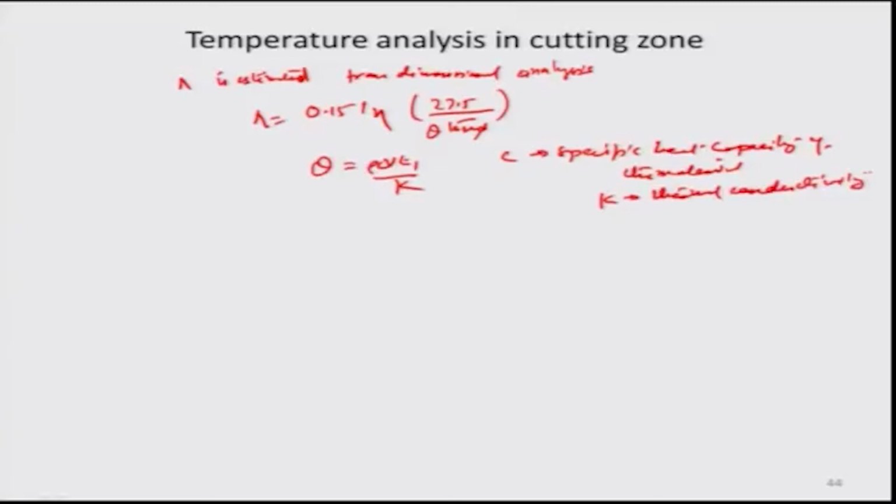So you have to create these non-dimensional quantities and find the relationship between this fraction of heat release and this whole quantity here. It is found from experiments, as well as from the non-dimensional parameters related to each other, that lambda is inversely proportional to the ln of theta, this non-dimensional parameter here, and also inversely proportional to tan phi, which is again non-dimensional in nature.